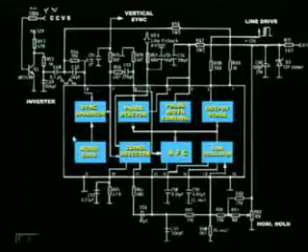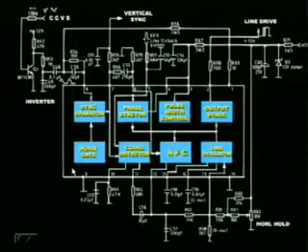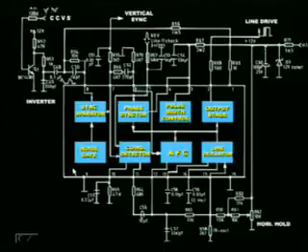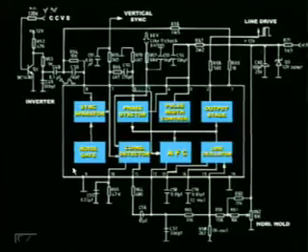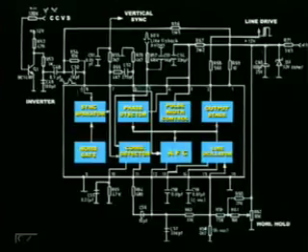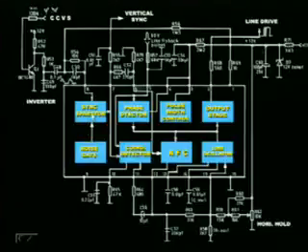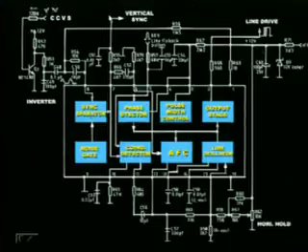Fortunately, this noise gate is available on the video ICs meant for sync separation and horizontal and vertical oscillator. If you see this figure, the noise gate is here and the sync separator is here. They feed the inverted pulse to the sync separator to reduce the noise level, and we get the horizontal and vertical sync free from the noise pulses. So, this was one of the circuits taken from the television.